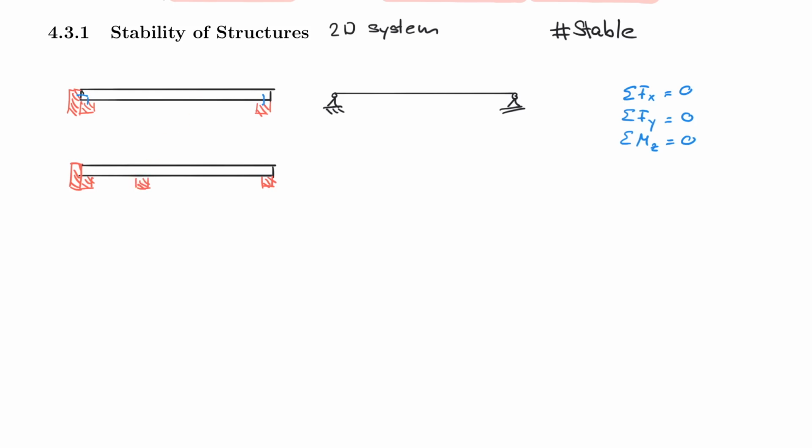If we were to draw this like engineers do, then of course the system would look very similar to what you have seen before, but with one added support reaction here. And be careful, this support here sits underneath the beam, so it's not a circle through, right? So please understand that this here sits only underneath the beam and not in the beam. That makes a difference, as you will see later throughout the lecture.